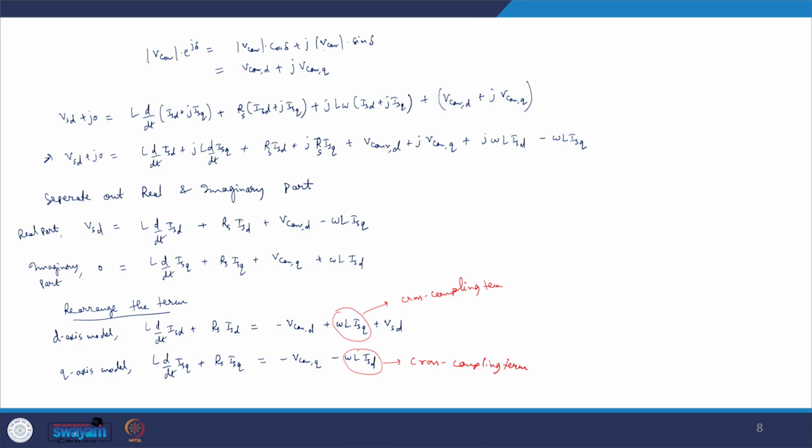That is when, in the three phase system, we will reflect that independent control by making sure we have balanced three phase operation, because we have derived the Q and D components by assuming that we have balanced three phase operation.